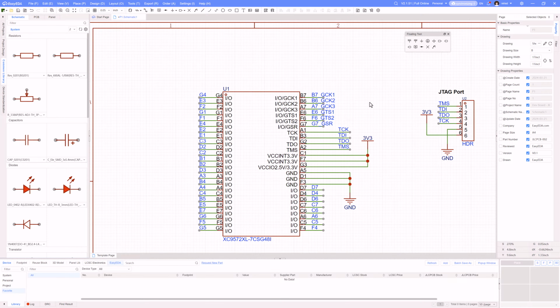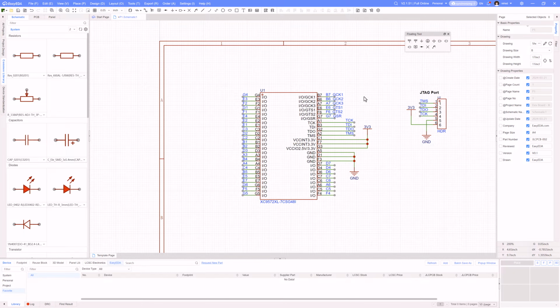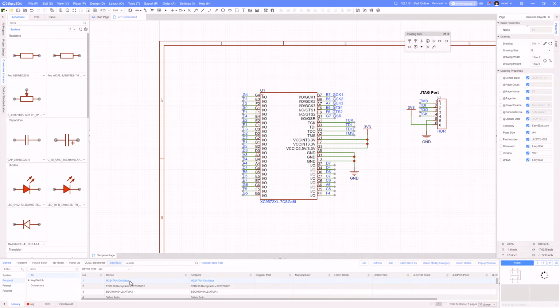And I'm pretty sure with the CPLD, I can feed it a clock. And I've got these 3 lines that appear to be global clock lines. So I might use one of those and just bring out an oscillator. Now, in my case, I'm going to go down to my library down here. And if I go to personal library, these are just components I've built, and there's actually a little oscillator that I've already set up. This is a component I created for this oscillator that wasn't in the library from the system. So I can place it